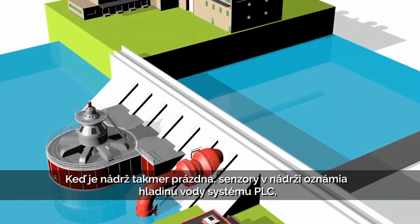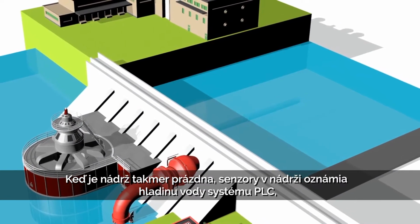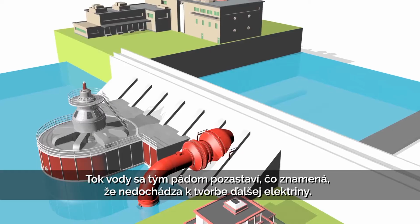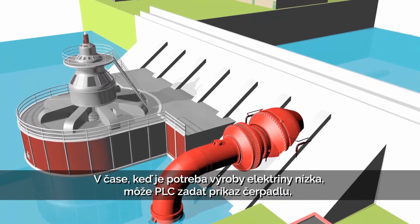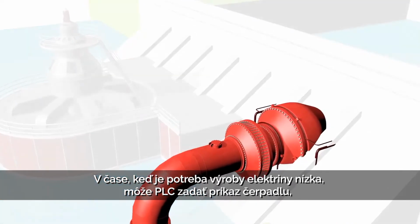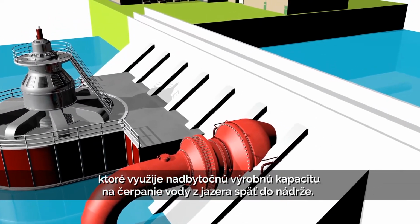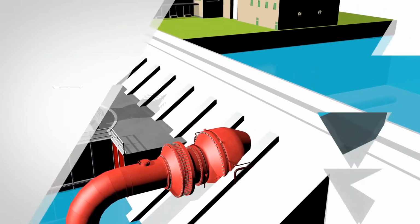When the reservoir is almost empty, the sensors within the reservoir communicate the water level to the PLC, which then commands the valves to close. This prevents the flow of water and thus no electricity is generated. At times when the demand for electricity is low, the PLC can command the pump, which uses excess generation capacity to pump the water from the lake back into the reservoir. This is the typical scenario of a water dam.